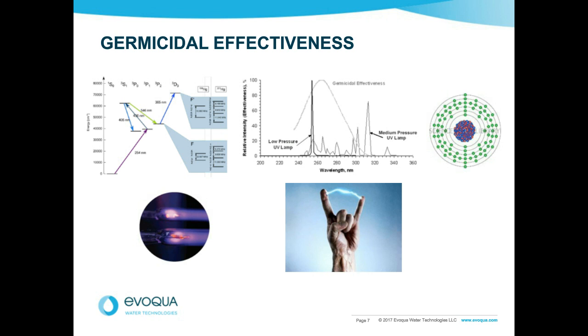So typically you'd have an old low pressure system without proper wipers, and you then put the water in a pond or a tank exposed to sunlight. The water hasn't received a high enough dose of UV because there were no wipers or the system wasn't being wiped. And then it's stored in sunlight because sunlight can trigger these processes. So the answer is very direct and very simple. Put it in a pipe, use medium pressure equipment, make sure you've got effective wipers, and keep it dark. And then repair doesn't occur.